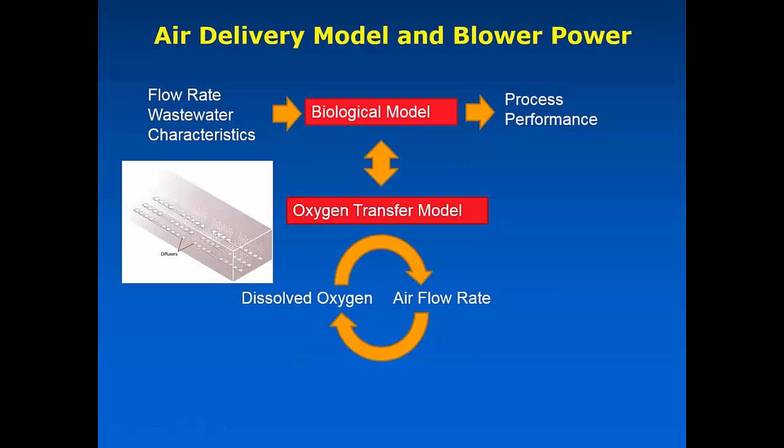The biological model, of course, will predict what the oxygen requirement is with the OUR, and then you can use your transfer model either working from specifying an airflow rate or specifying a dissolved oxygen concentration with your DO controller, and those sorts of things will transfer a certain amount of oxygen to that system, and then of course that predicts performance.